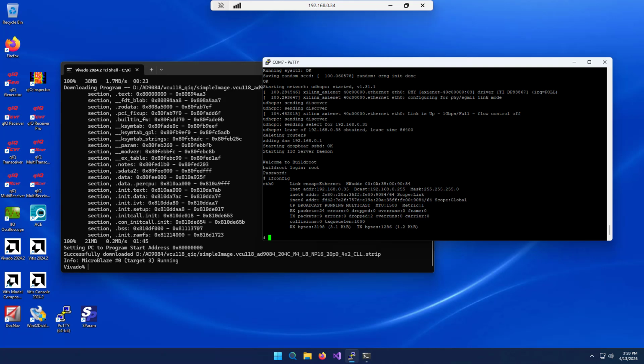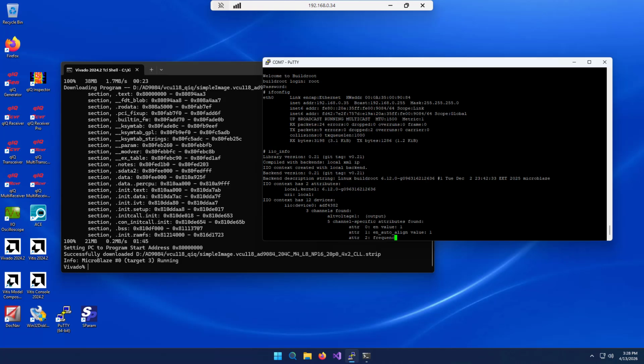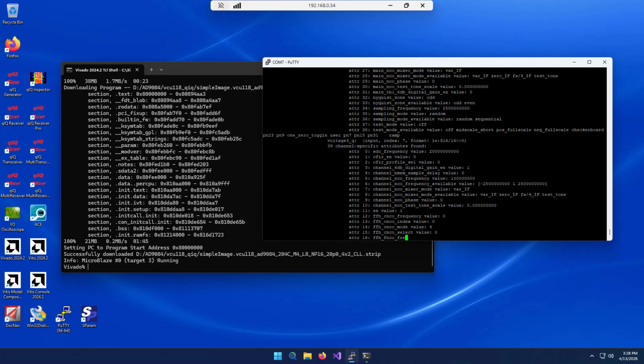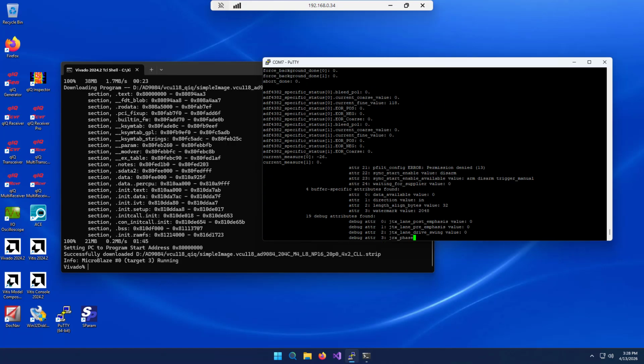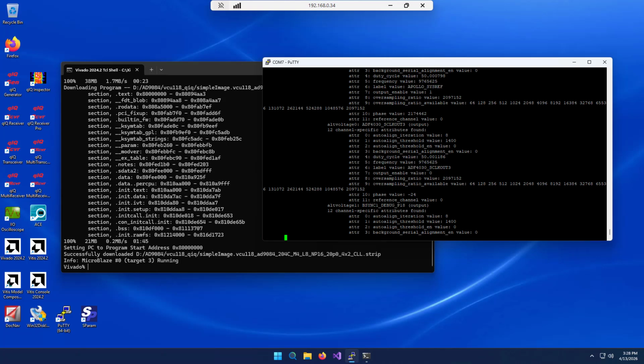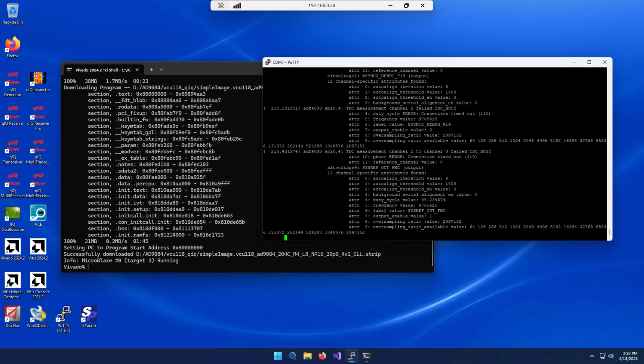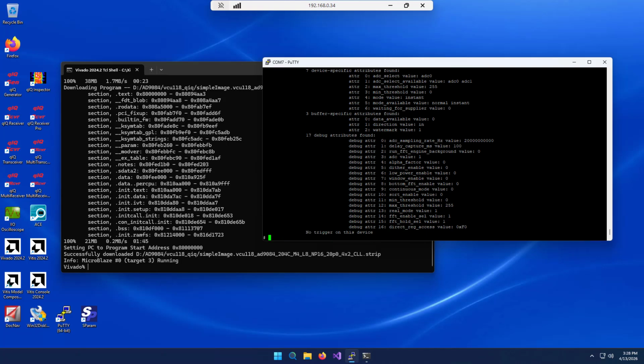So one of the things that I like to do at this point to just verify that the system has been loaded correctly and is running correctly is I do an iio_info and have it tell me all the IIO devices that it found. And I can tell already that this has been successful. It's going to go on for quite a while and list for us all of the IIO things that it found as it was setting up the system.